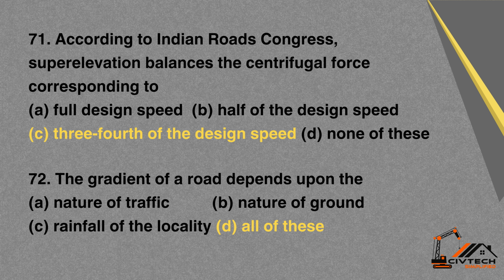71. According to Indian Roads Congress, superelevation balances the centrifugal force corresponding to A. Full design speed, B. Half of the design speed, C. 3/4 of the design speed, D. None of these. Correct option, C. 3/4 of the design speed.